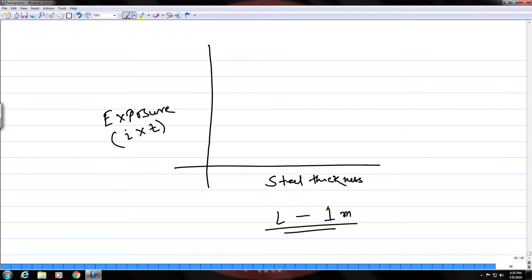So, it can be done for example, on a steel sample for a fixed sample to source distance of 1 meter, and then you vary the thickness and obtain the data, and when you plot the data at different tube voltages, this kind of curves will be obtained.